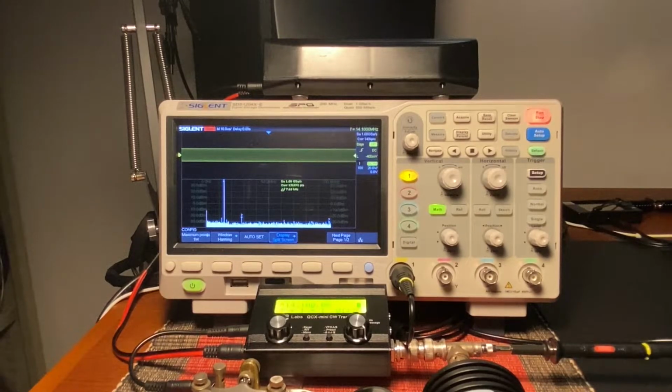The transmitter signal must be properly sampled, attenuated, and protected from interference, and the parameters of the analysis must be carefully chosen or the results will be misleading. Internal artifacts generated within the scope need to be identified and accounted for. All devices have some such spurious signals. RF spectrum analysis requires attention to detail. The dynamic range of the analog path can limit the ratio of fundamental to harmonics we can display. With care, we can achieve a 60 to 70 dB dynamic range on this model.